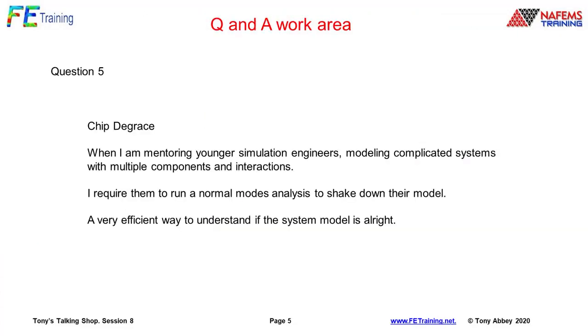Chip makes the point, when I'm mentoring younger simulation engineers, modeling complicated systems with multi-components and interactions, I require them to run a normal modes analysis to shake down their model, a very efficient way to understand the system model. It is. I completely agree with you there, Chip. I've been focusing on dynamic analysis and dynamic response and saying this is important to understand what's going on. But in fact, any structure, even if we're going to do a static analysis, I use a normal modes analysis as a shakedown to make sure I understand that structure.